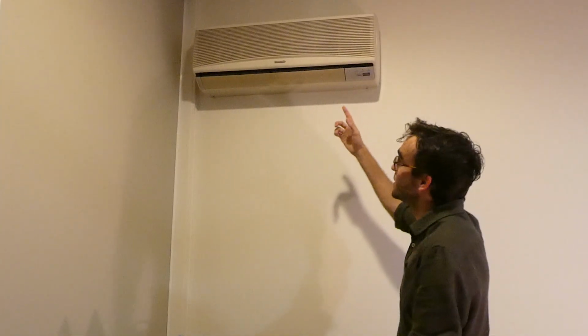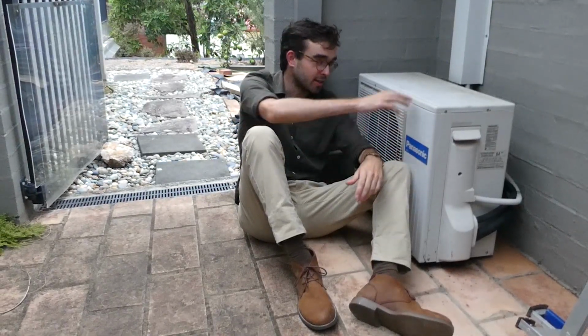With the heat removed, the cool air is then circulated around your room with the fan in the aircon. So that's all the cold air that we feel blowing out. Finally, the refrigerant gas returns to the compressor and starts the cycle all over again. This continuous cycle of compressing, condensing, expanding, and finally evaporating allows air conditioners like this old box sitting here to keep a constant temperature in your room.